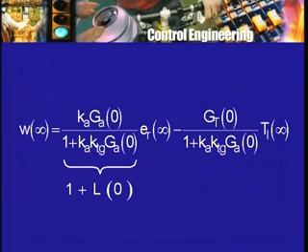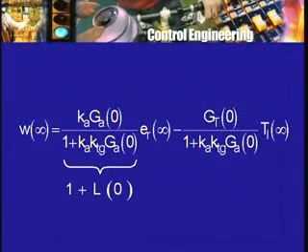The signal E that I talked about earlier, the output of the comparator, will not be 0, but that is not a steady state error at all. There is no steady state error at rated torque conditions. However, when the reference voltage is kept unchanged, of course, and the load torque changes, then there will be a change in the speed, or there will be a steady state error in the speed. However, this steady state error in the speed when the load torque changes will be much less with feedback than what it would have been without feedback.